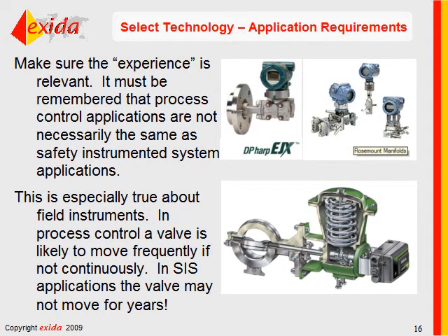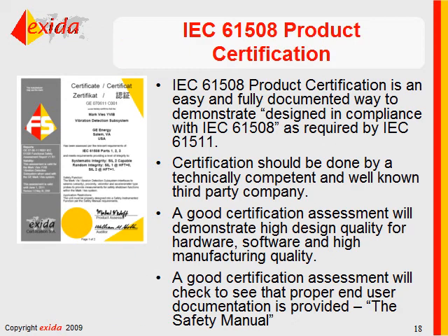If the process has been designed well, and we rarely ever get a dangerous condition, that valve may not move for months, maybe years. Those stress conditions are quite different than conditions where a valve is being used in a control application. So be careful to make sure that you're thinking about similar application conditions.